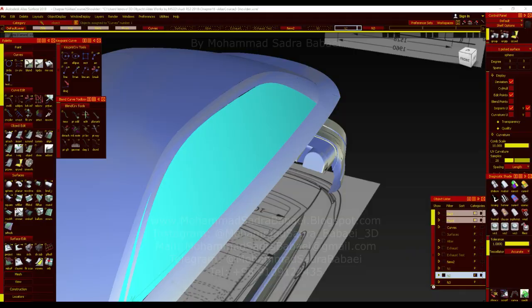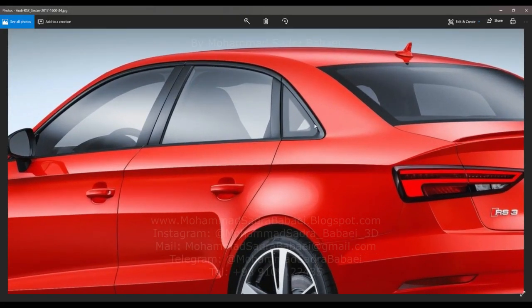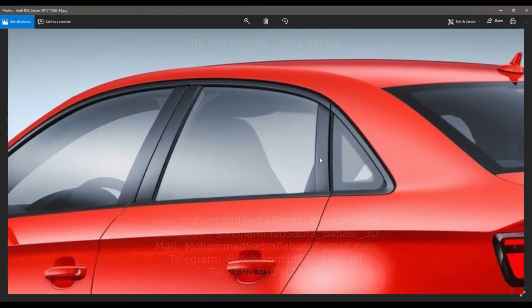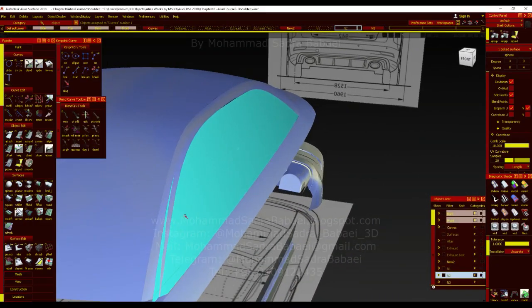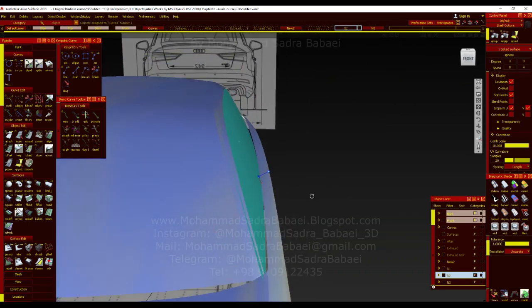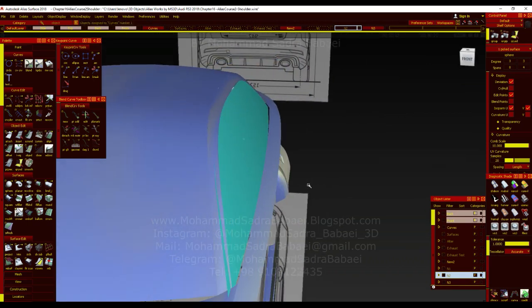You can also use this surface to intersect the pillar, offset the curves here and create the wireframe, and move the glass inside a little, for example 3 millimeters inside, so you can create the details there.